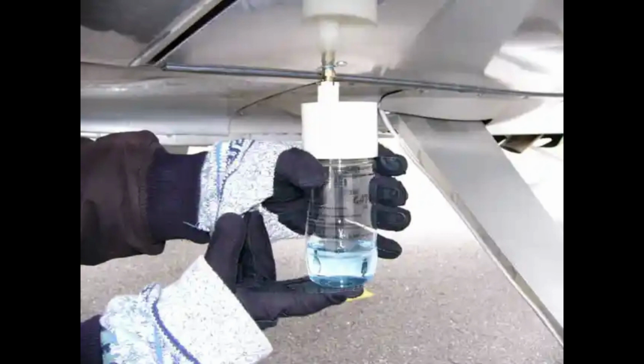If it is not feasible to drain the fuel, the tanks can be topped off to be sure of the quantity they contain and the aircraft weighed with full fuel. After weighing is complete, the weight of the fuel and its moment are subtracted from those of the aircraft as weighed. To correct the empty weight for the residual fuel, add its weight and moment.